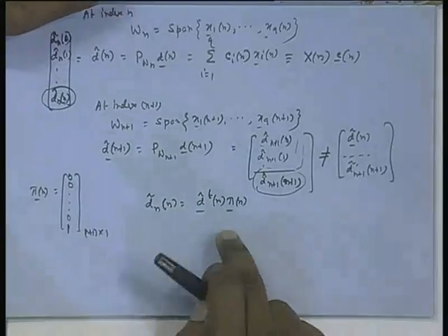That is the entire approach. And you understand this journey will take us to the optimal ones: C vector n, then C vector n plus 1, then C vector n plus 2. As more and more data are used in computing epsilon n square, it will be a better and better estimate of the original epsilon square, and therefore this coefficient sequence will march finally to the optimal ones, exactly, not in mean, unlike LMS. And no searching business; it will march very fast. So this is what it is.